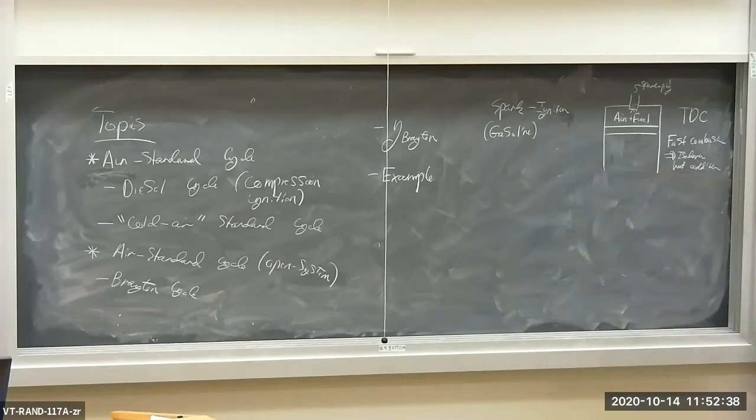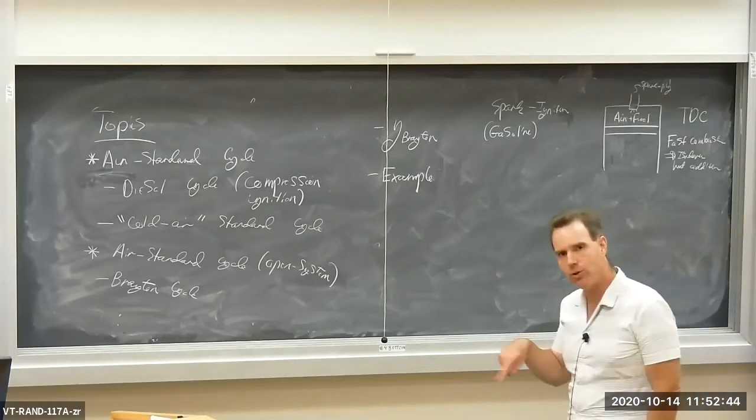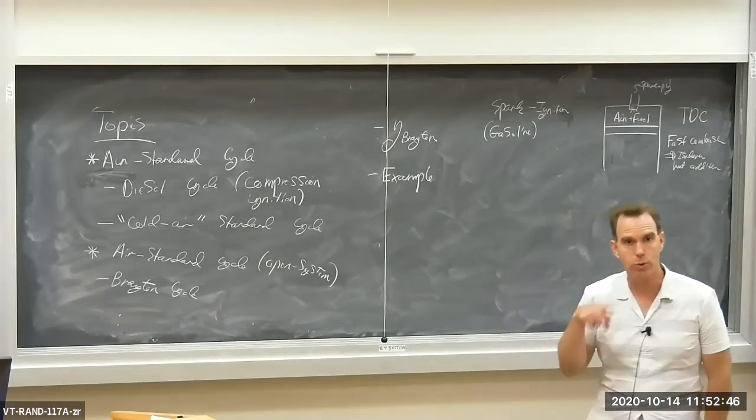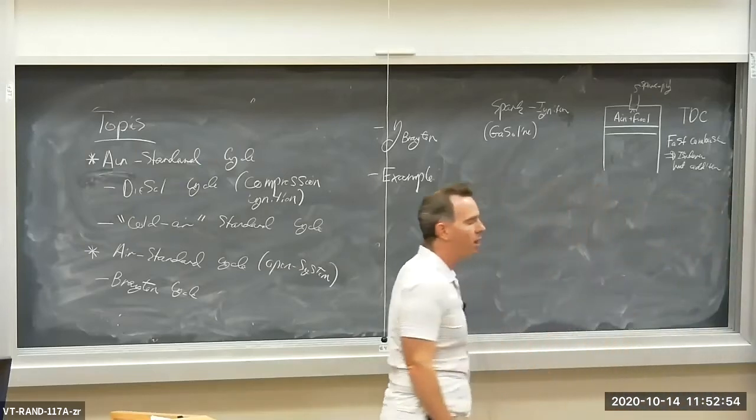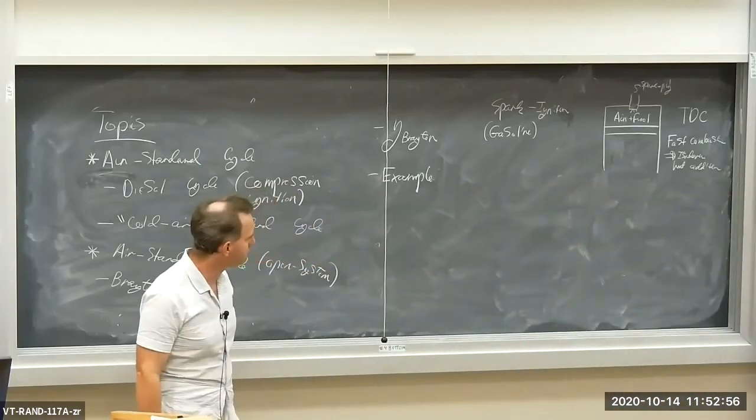Okay, so that's what happens with the spark ignition or gasoline engine. A very fast combustion process, faster than the rate at which the actual engine is turning in terms of RPM. The combustion process is much faster than the speed of the engine, so we assumed it was constant volume combustion.